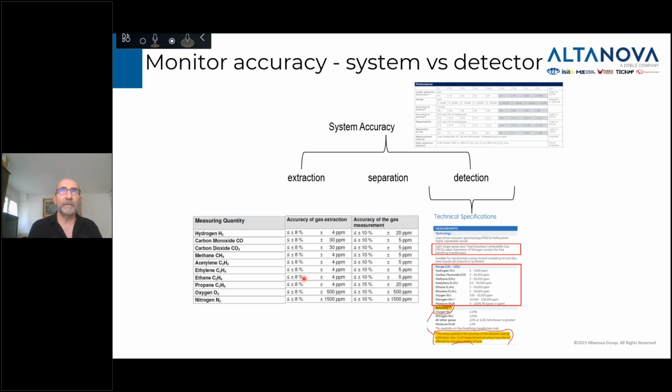So right at the beginning, you're outside the IEC spec, and it tells you that whatever comes out of that specific equipment, the measurement is not going to be highly accurate. And also you have to do the same thing, sorry, on the LDL. What you see here is that for the majority of the gas, the LDL is around 9 ppm, and for the hydrogen it is 24 ppm.